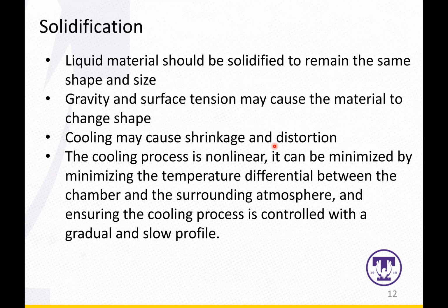So that will be a very good setup for the machine to control the surrounding temperature, and that could improve the quality of the printed products. But for most of these consumer-level ones, you have to cool your printed layers by interacting with the surrounding atmosphere.